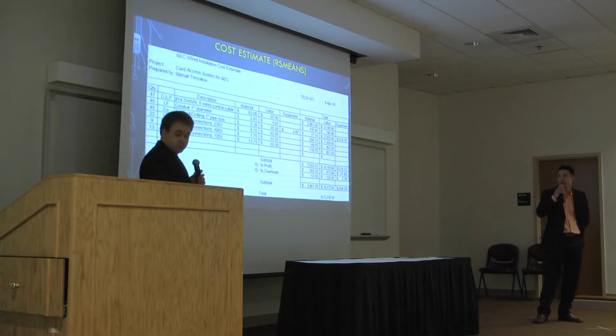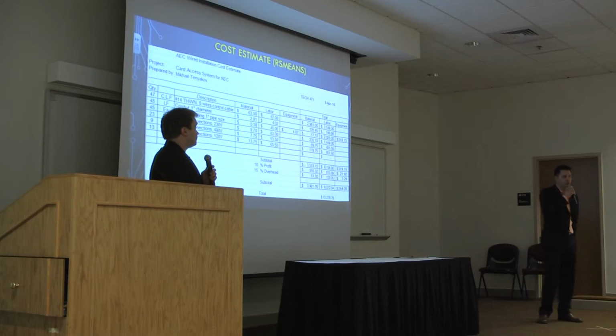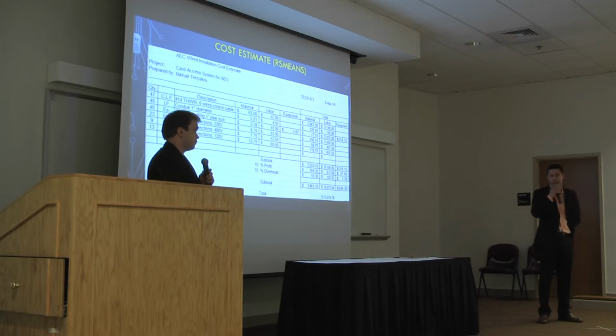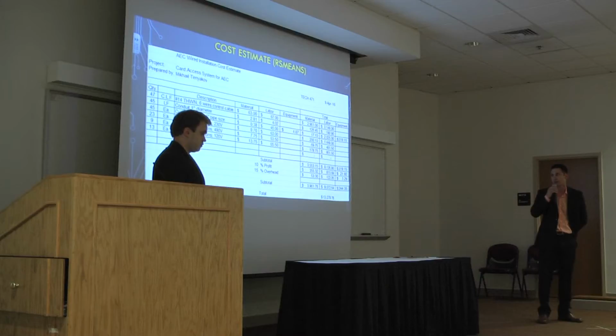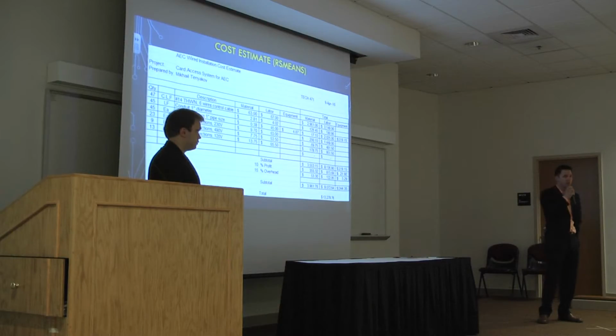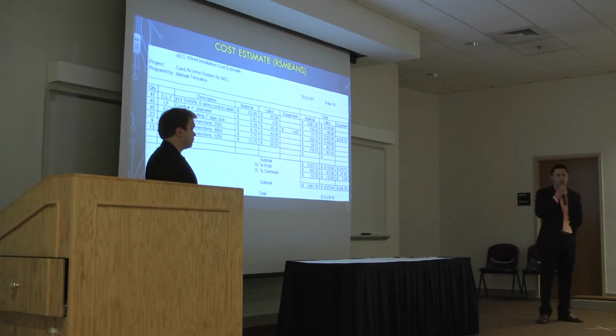With this information and being prepared, also by using AutoCAD and the exact locations of the machines, we were able to map out exactly how many feet of wire and conduit and everything else we would need. We used the RS Means estimation book to come up with our costs. This doesn't include high voltage control panels or any of the hardware that's associated. This is just the wiring and conduit alone if we went with the wired option. And it comes out to about $13,300.